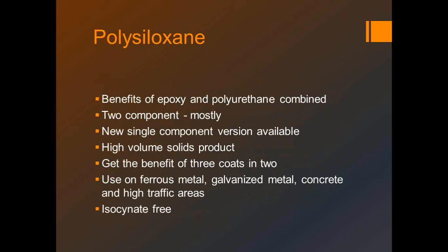Now, I'm sorry. When you go on a galvanized surface, you still do need to have some sort of wipe down with an etching material. Yeah, the more profile we can get to the surface, the better off we're going to be. Well, and remove any residual grease and oils from the forming process, isn't there? Right, and we need at least SP1, which would be solvent wipe down.